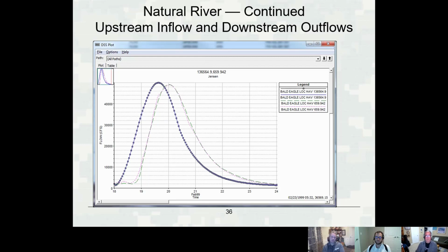So intuitively, I want to say, correct me if I'm wrong, Gary, but with the finite volume approach, it's even more important that you have cross-sections spaced closer together so that you can approximate that volume. It depends on the slope of the water surface, first of all. If you're in a flat area, you can obviously still have cross sections really far apart. If you're in a steep area, yes, you want tighter cross sections.